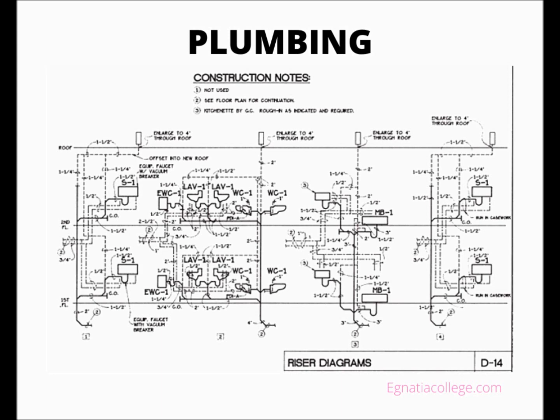Although the storm drain and the sanitary drain pipes cross near the janitor's closet on the first floor, they are not connected. In the region where this building was constructed, drainage pipes outside the building lines are installed by the site contractor, not the plumbing contractor. Therefore, the plumbing drawings only show the storm drain and sanitary drain to 0.5 feet outside the building lines. A note where each line passes through the building wall indicates the invert elevation of the bottom of the inside of the pipe.